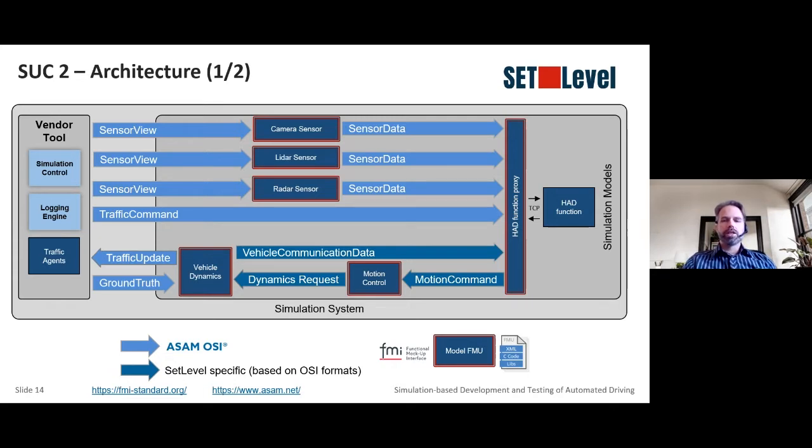The model integration was done using another standard, the Functional Mockup Interface, or short FMI. Using this standard eases the integration and improves flexibility. Only the highly automated driving function couldn't be implemented as a functional mockup unit, hence a specific proxy serves as a gateway. All FMUs are marked with a red borderline in the architecture sketch.